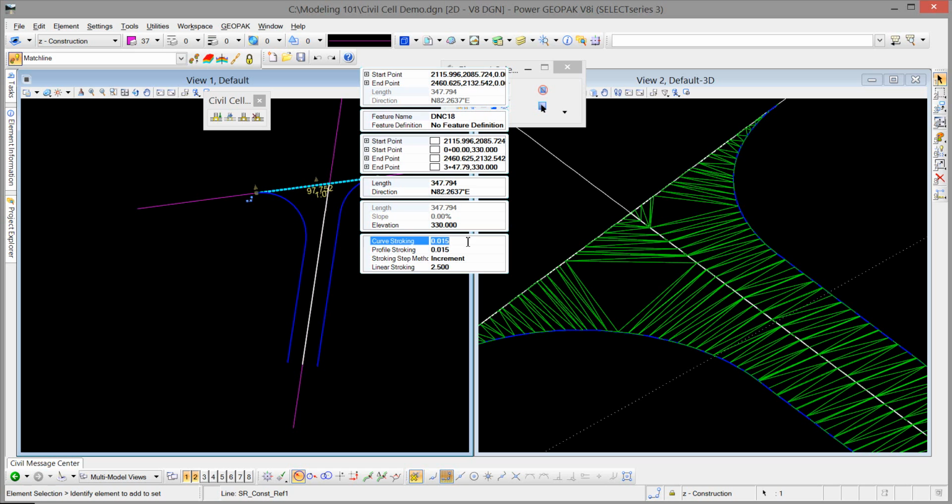What if, remember, this is taking on the real edge of pavement. What if that's going through a spiral or a taper and it's not a straight line? Well, then I should really be consistent here, right? And set those the same as what I'm doing for the rest of the boundary of that terrain. Okay? And so I'm going to set that back to 5. But if I say 0.01, 0.01, and 5, then make it that way all the way around.